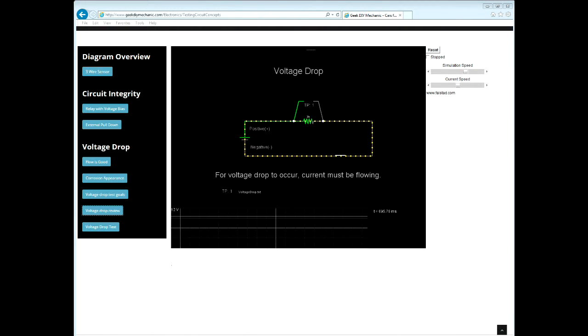Now, let's see what happens when we open the ground side switch, called ground side since the switch is after the load. Load is before, thus ground side switch. Since there's no current flow, notice that the voltage stays constant all the way to the switch. So from the positive point of the battery, it goes all the way across to this test point, across the load with no voltage drop because no current is flowing, all the way to the open in the circuit.